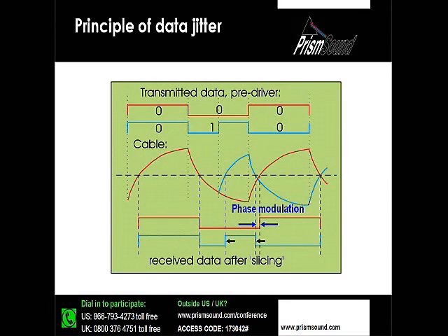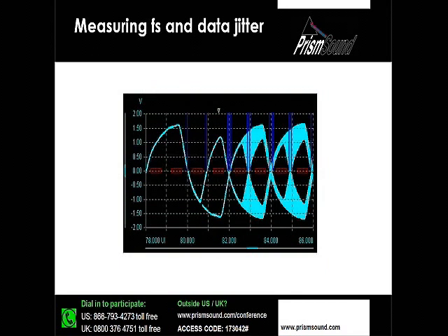Now, measuring this jitter is very important because obviously, if you have jitter, you want to know whether or not it's coming from a clock or from a cable. But this is not very straightforward when you're looking at the eye pattern. In fact, when you look at a typical eye pattern, and if you're in the audio portion, the jitter that is represented by the width at zero crossing is actually the combination of clock jitter, FS jitter, and data jitter.